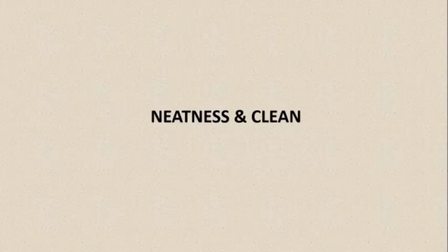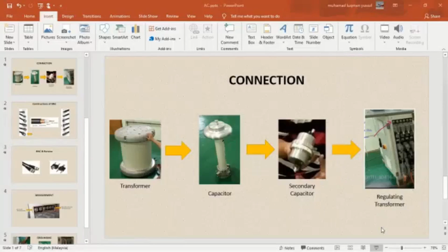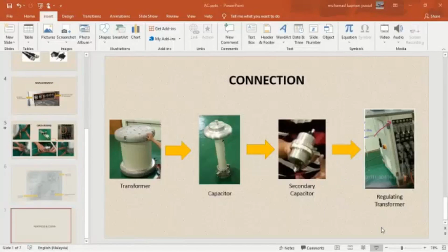The third one is to maintain regular cleanliness. This involves much more than a spray bottle of cleaner and a rag. Clean rooms require special housekeeping procedures, schedules, and materials to keep surfaces contaminant-free. That's because certain floor finishes, chemicals, vacuums, mops, and sponges can actually be a source of contamination. Keep up to date on your clean room classification with help from professionals to determine which cleaning chemicals are appropriate for your space.